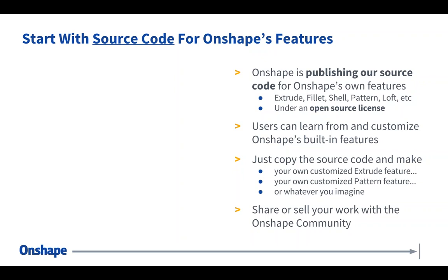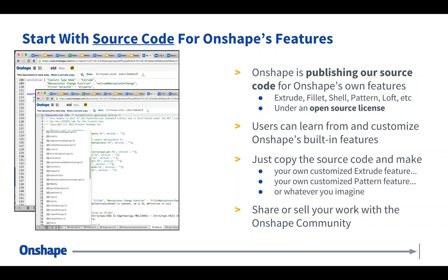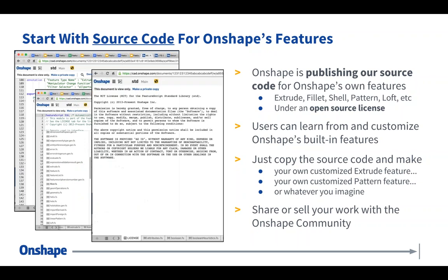Now, as I mentioned before, you can start with the source code for Onshape's features. So this is our standard document, and it has within it all of our standard features. So there's the source code for our fillet feature, for example, or extrude command. And all of it's being released under an MIT license. And the reason this is important is it means you can freely access it, you can create features based off of it, and either distribute those freely or even monetize them if you choose to, which means you could write a custom FeatureScript feature and make money off of it.